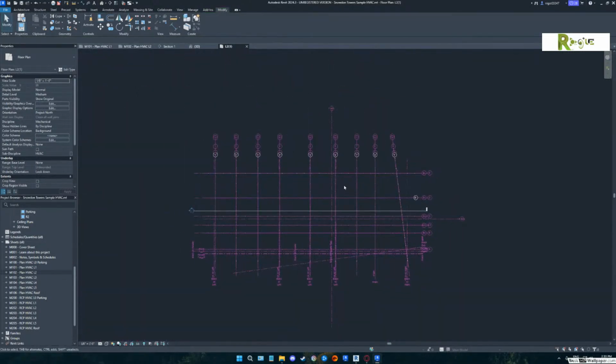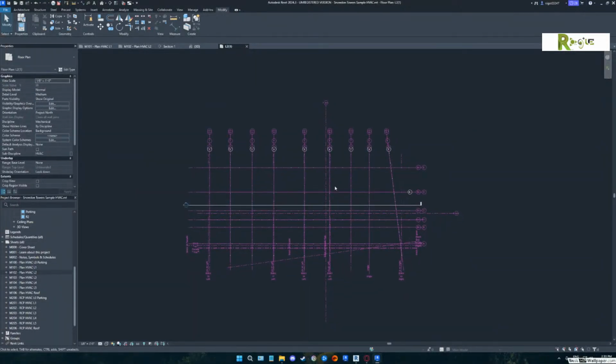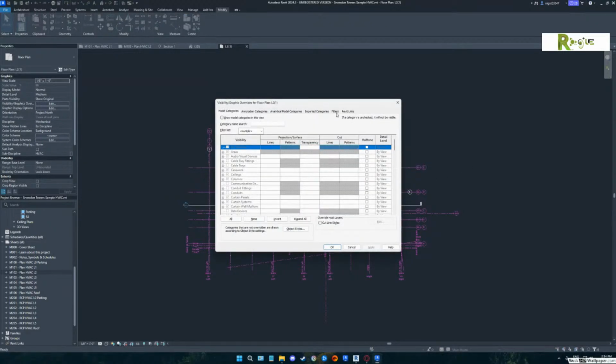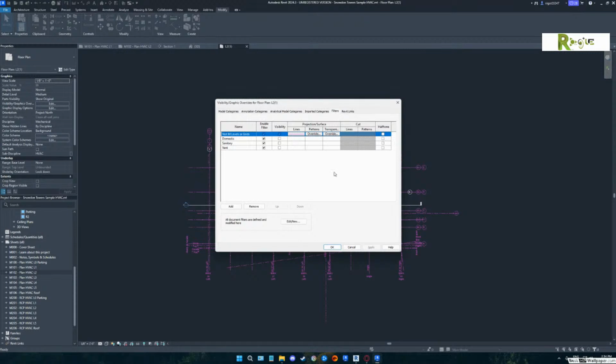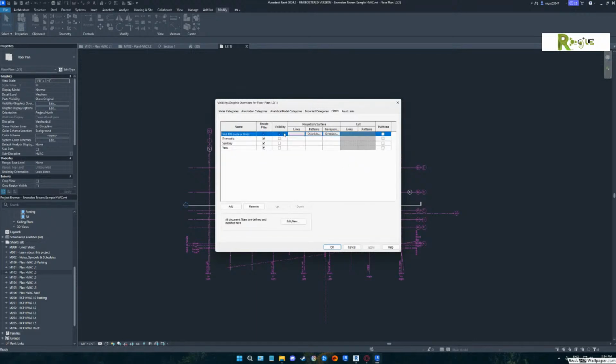Okay. Yeah. That's a common problem that you can get because you don't have that problem if you have that locked linked files on, because then you don't accidentally move it. So this would be a great time to turn the locked link off. But sometimes we need to turn that locked link off so that you can select the object to find out what that thing is. And then there you would just turn the visibility off for those in all your other views.